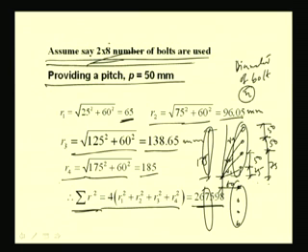Only after assuming the number of bolts will we be able to find out what the diameter of the bolt should be. In case of rivet, first we find an approximate number of rivets, then accordingly we design and specify.